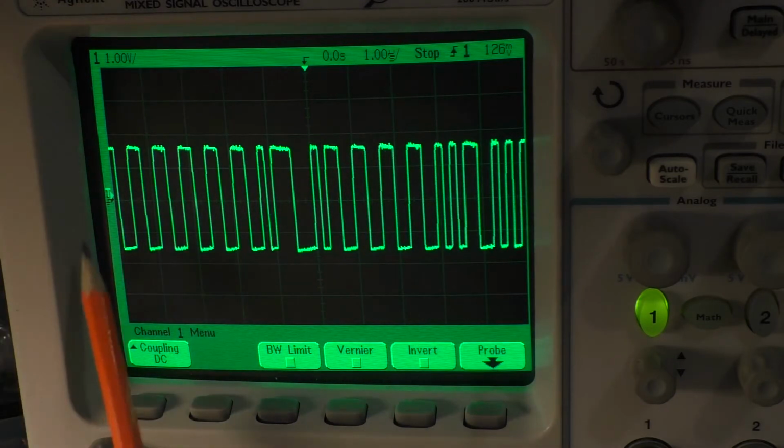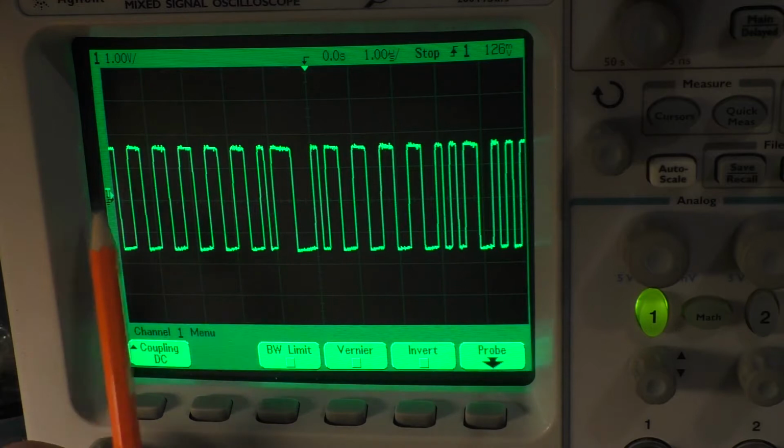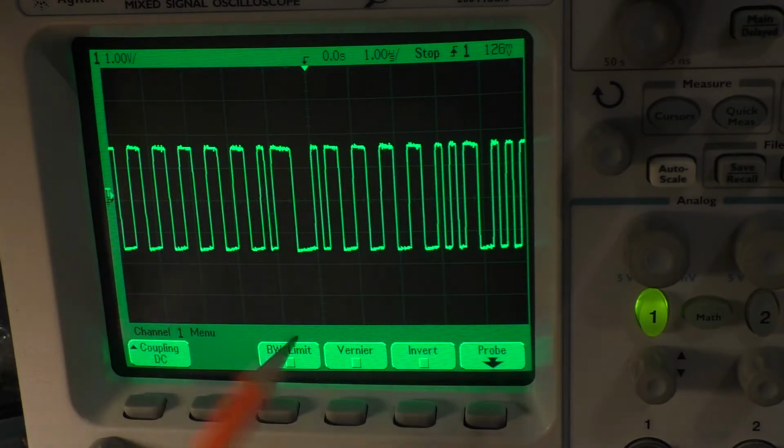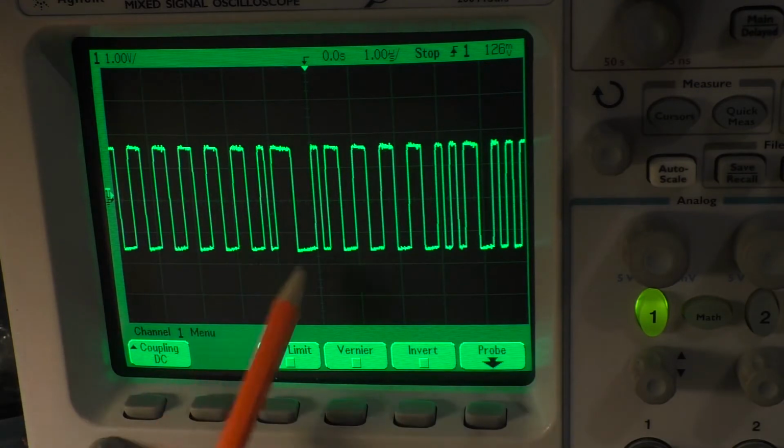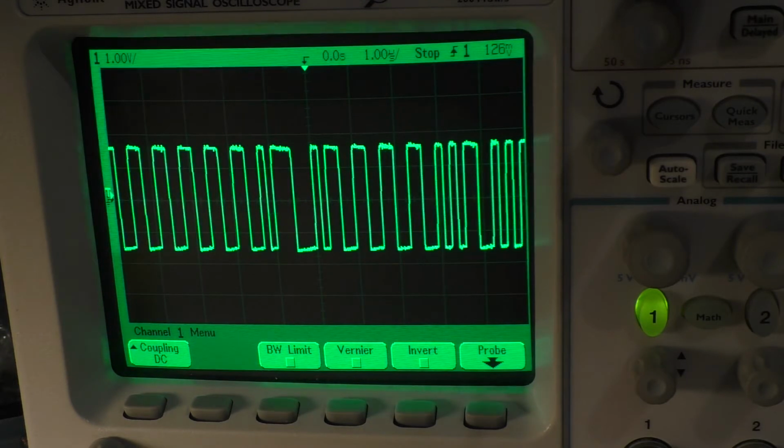In case of zeros, this is just your bit clock, and then you synchronize to this bit clock, and when you're looking for a 1, you're just searching for that extra transition. Thanks to that, you only need to carry 1 signal instead of 2 signals, and you don't have clock skew because the clock is encoded in the actual data signal itself.